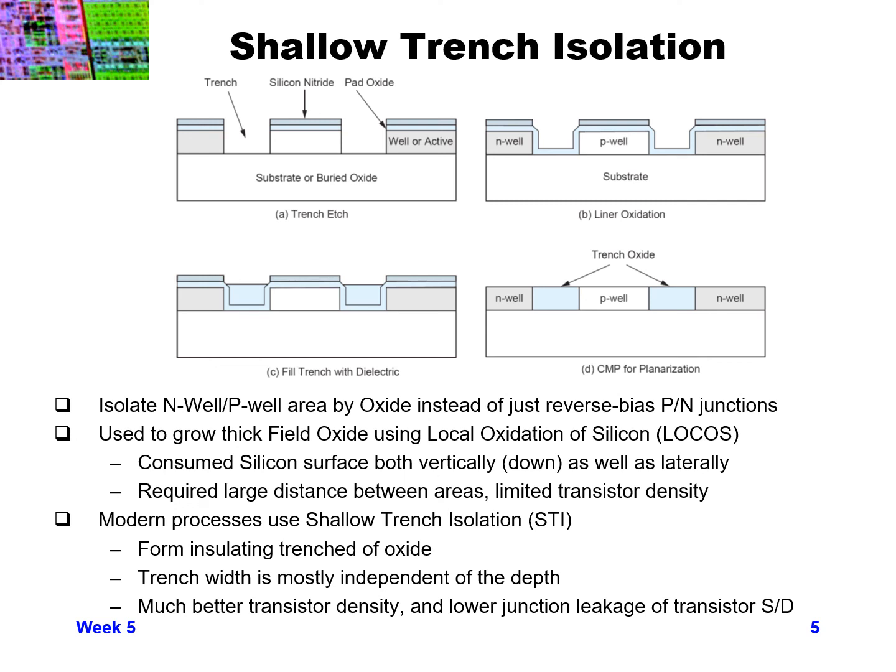If you see in the diagram above, we have some different well areas, an N-well area and a P-well area. And in older process technologies, we used to just grow a really thick oxide that goes all the way down the depth of the well, but then that caused lateral diffusion of that oxide. So there was a fairly large distance between P-wells and N-wells.